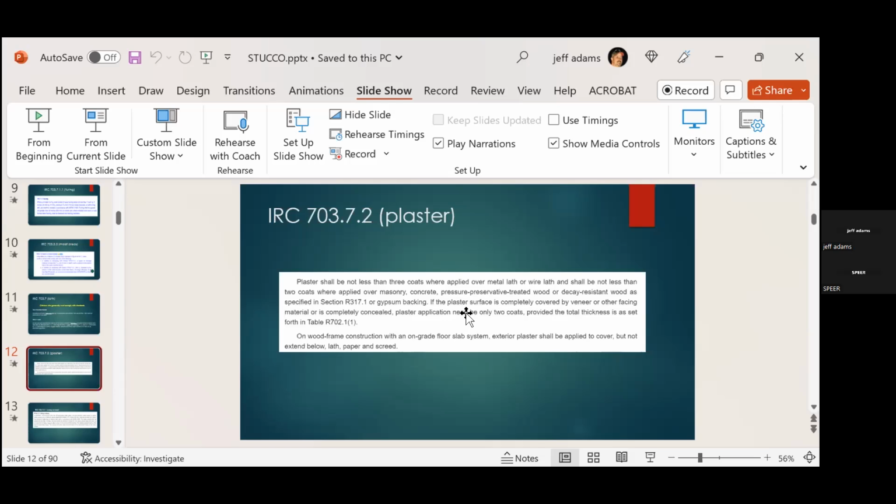There are still a few builders out there using Paperback or some of the other products that are out there, and they do work, but you have to really watch how they use those. Make sure if they're a tongue and groove type of gyp board being used as WRB, that tongue and groove is installed properly. Sometimes they install it upside down, and it will not prevent the water from entering the wall very well when you do that.